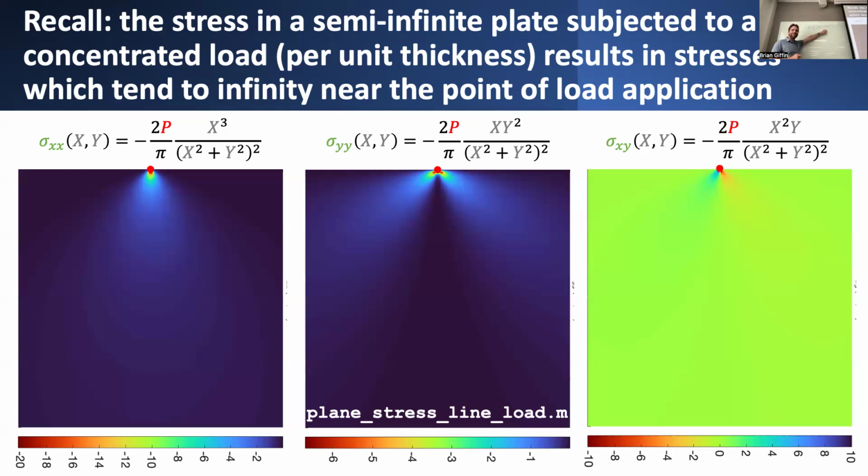So we've ruled out compatibility, or the strain displacement relationship, as the problem. If equilibrium wasn't satisfied, then our fundamental understanding of physics is flawed, so I feel like we should keep that one around. The only remaining suspect that we haven't ruled out yet is the constitutive law, or the relationship between strain and stress. Now, I'll give a moment to think about this.